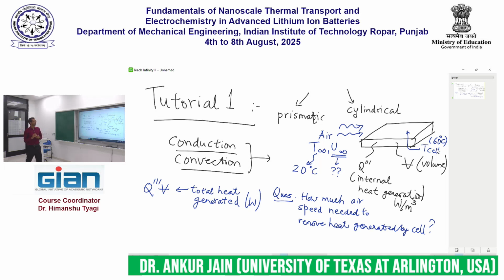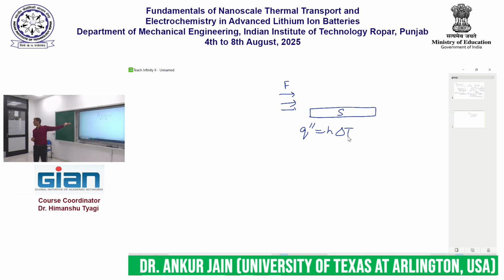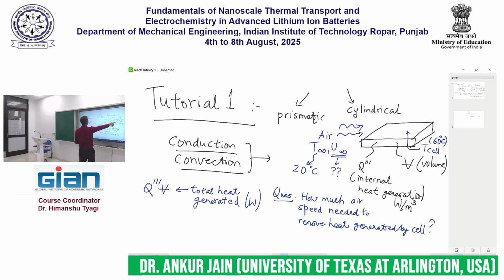To answer that question, we have to appeal to some of the heat transfer theory that we have learned in our previous class. Earlier we had learned that if I have a solid body and a fluid passing over it, then the amount of heat transfer that occurs is given by H delta T. That is the equation that will help us here. In this case, delta T is T cell minus T infinity.